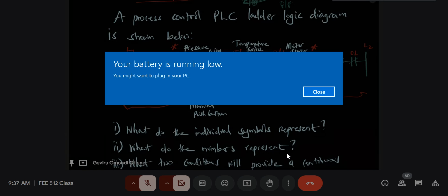So the input module of the PLC is the one that is responsible for knowing that we have a physical switch here, I1. Its state should be transferred into the program as I1. So the memory address I1 should have the same contents as the state of the physical switch. And who determines that? The input module of the PLC.